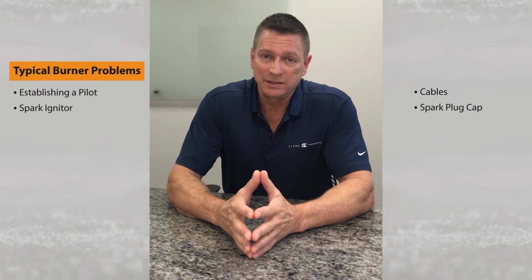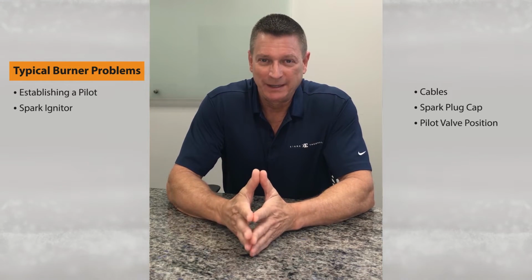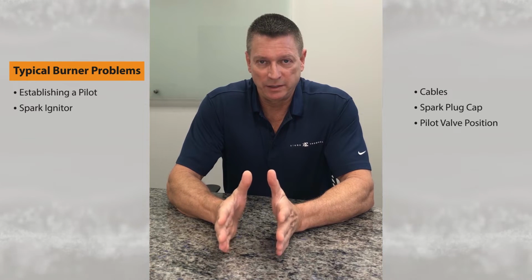And that nobody has accidentally closed a pilot valve. Believe it or not, that has happened before. So you want to make sure that everything is normal and all the valves are open, pressures look good, and that will solve a lot of the PTFI flame fails.